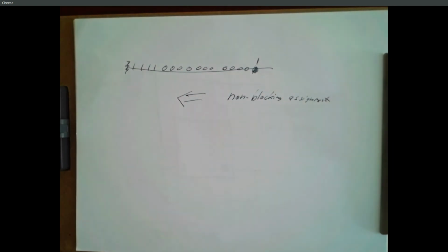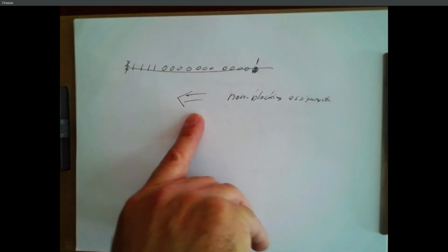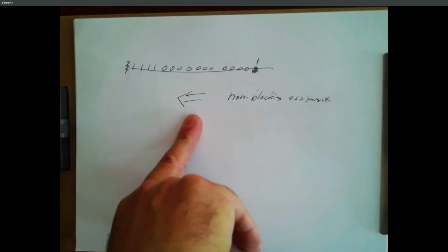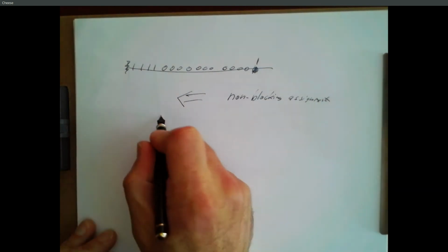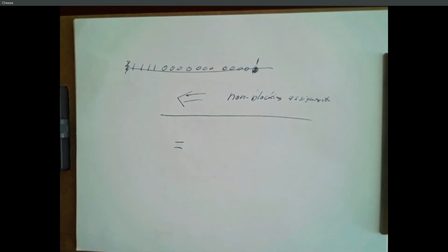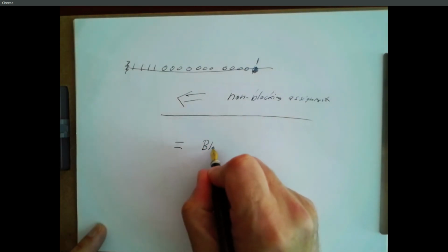So hardware is inherently parallel, and we like to build hardware circuits to take advantage of that parallelism. And if you use these non-blocking assignments, you maintain that parallel behavior of your circuitry. Now, if you use an equals sign, that will work inside an always block. It will copy the thing on the right to the thing on the left, but this is a blocking assignment.